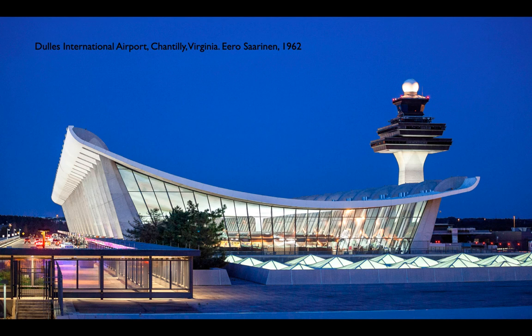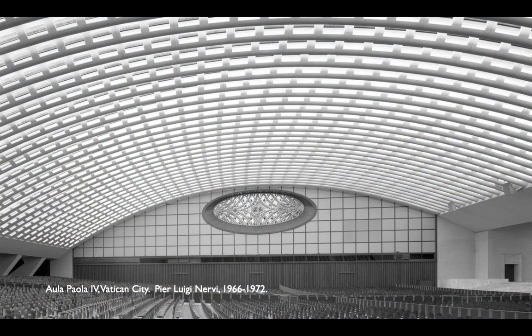So here, Eero Saarinen's design for Dulles Airport in Virginia, Saarinen doesn't really have the option of choosing the curvature that he wants. He can pick the size of the towers on either side, but because this is a cable structured system, he's pretty much stuck with a catenary shape, right? A curve that the cables are going to take almost kind of no matter what. So the architecture very often in long spans follows from the structural principles. That maybe we're kind of used to.